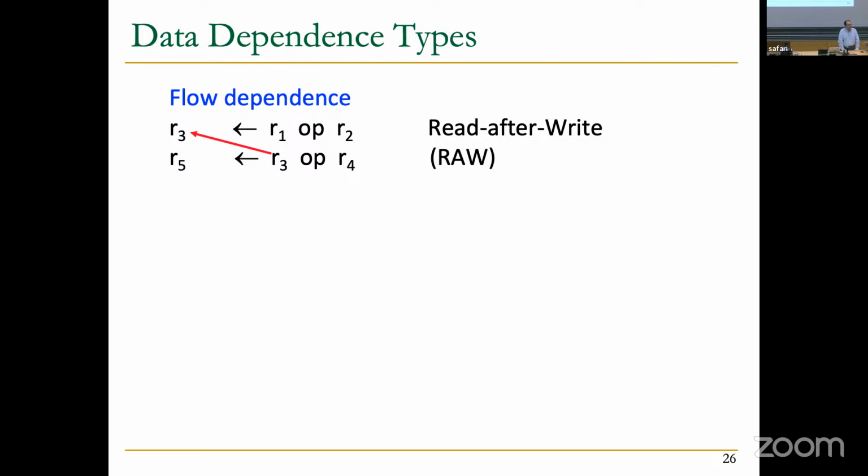Did you get what I'm trying to say? So they can be multiple registers? Yeah. In the design, you can consider that you have a bigger register, like, let's say, a 128-bit wide register, and then use it for tag and data and so on. Or you can have multiple registers, but all these multiple registers can be accessed with the same address.